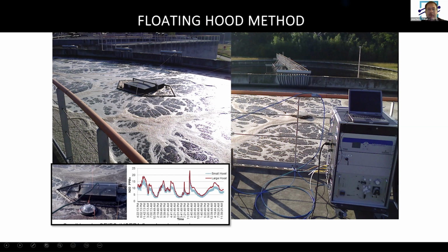One thing you also have to be careful of is the rope tying and securing the hood. You need to leave enough slack in the rope, especially if there are possible changes in water level. If the water level can change significantly based on the incoming flow, you want the hood to be able to move up and down with the water level.